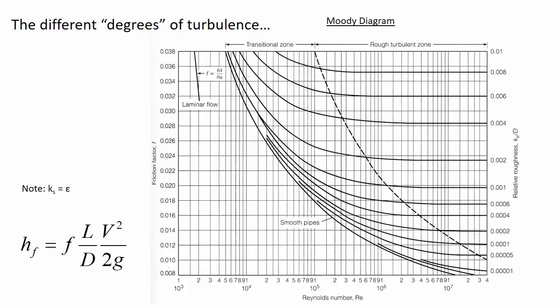Kind of by definition, it has to be. Otherwise, the water wouldn't be flowing from 1 towards 2. So the pressure is going down, and if we can estimate h sub f, that'll tell us the rate of pressure loss. So if you had some known pressure at 1, you could predict the pressure at 2 after calculating how much energy was lost due to pipe friction.